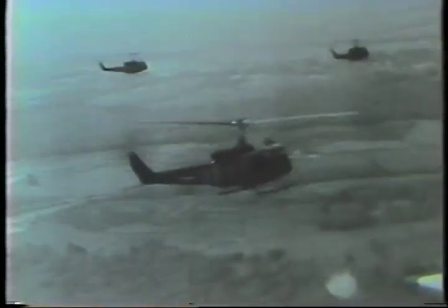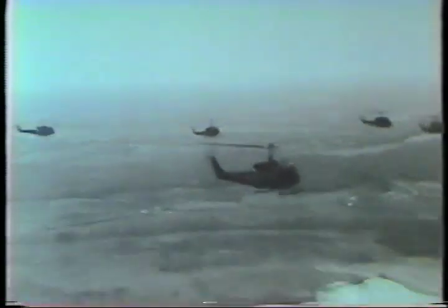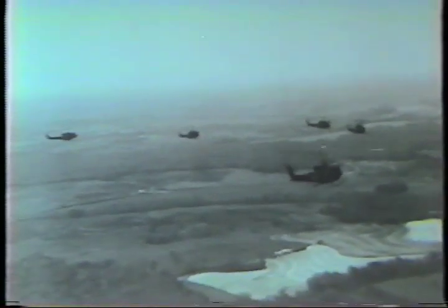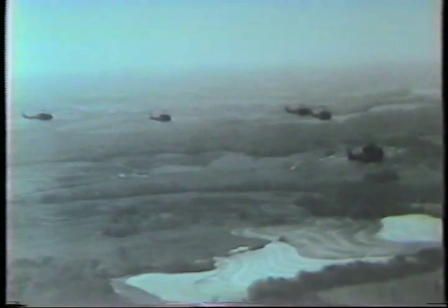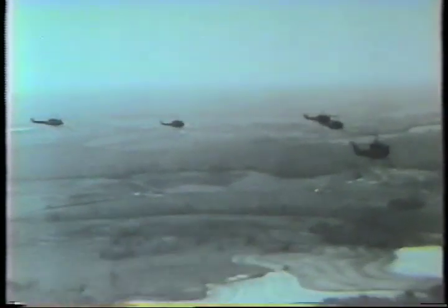The joining members of the flight will approach the lead aircraft by crossing his orbit at 70 to 80 knots and at the same altitude. As final join-up is completed, airspeed will be reduced and heading varied so as to close into position at 60 knots and 45 degrees astern of the lead aircraft.